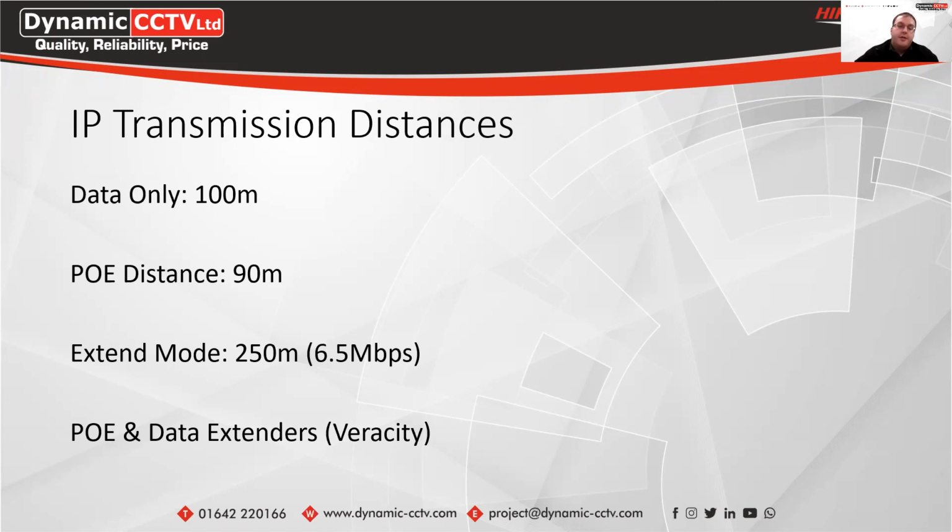We do also have a range of PoE extenders and data extenders from one of our partners, Veracity, and so these will also extend PoE as well as the data. So we've got inline units, we've got data only units, and we also have what's called a long span, which allows you to achieve really long cable runs between two long span units, a base and a camera side unit, and that will also transmit PoE down Cat5 as well. So you can actually still use Cat5 cable with those, and they're a brilliant bit of kit when they're needed within that.